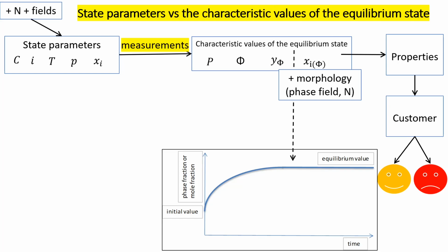You should cool very fast to make sure nothing changes during the cooling. And then you reach a temperature when all the processes are so slow that nothing is really happening. And if you reach that very cold state, then you can prepare your sample, and then you can analyze your sample using scanning electron microscope and X-ray diffraction, whatever.